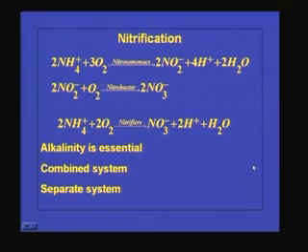So, who is doing the oxidation of ammonia to nitrate? Is it the heterotrophic microorganisms present in the system, or is it some other microorganism? What are the conditions required for the proper oxidation of this ammonia to nitrate? If the complete oxidation of ammonia to nitrate is not taking place in the treatment plant, what will happen? The effluent coming from the treatment plant, if you discharge it to the water bodies, will exert some oxygen demand. That is not advisable. So, complete oxidation of this nitrogenous material is also essential in the treatment plant.